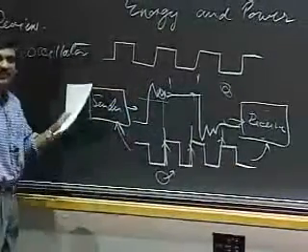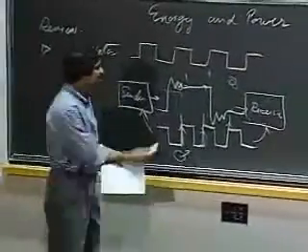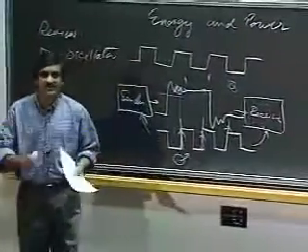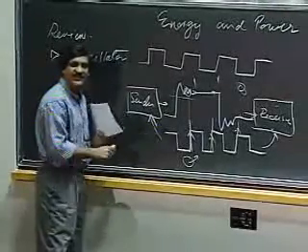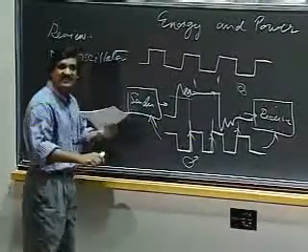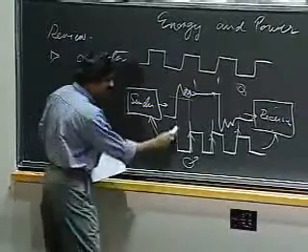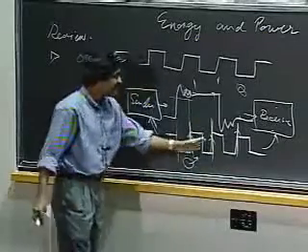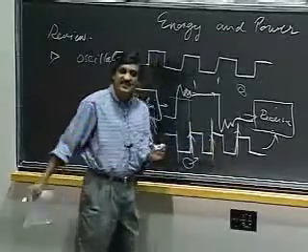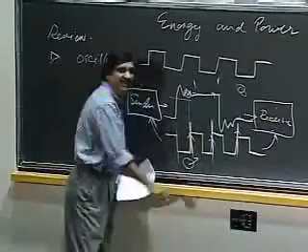What I'm saying is that, look, in the digital domain, we've already discretized value into zeros and ones. But we still had continuous time until now. And what we do in digital systems is to say that, look, let's discretize everything, and let's discretize time as well into these points that happen on the rising edge of the clock, which means that the circuit has meaning, signals have meaning only when the clock is rising.